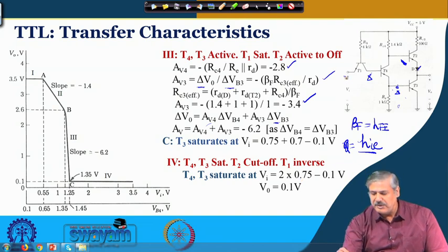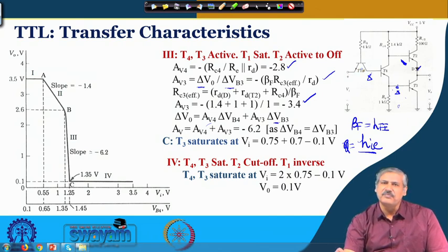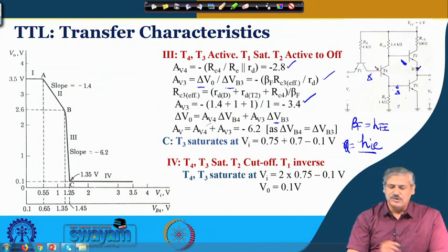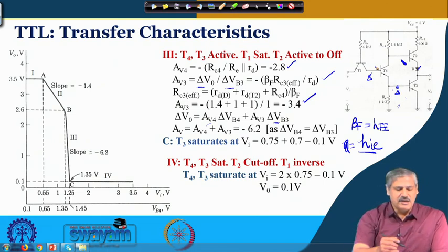And if you keep increasing the voltage, what will happen? This transistor will work in the reverse direction, sending current in this direction. This emitter will work as a collector, and this collector will work as an emitter, and the current will be going in the other direction. For that, the inverse beta will be a very small value. So, if you now look at the whole of it, the normal stable operations are region 1 and region 4.